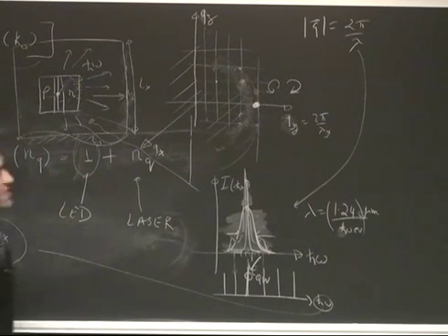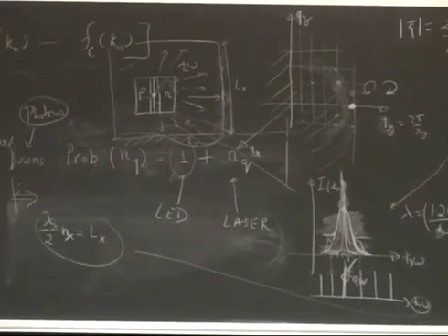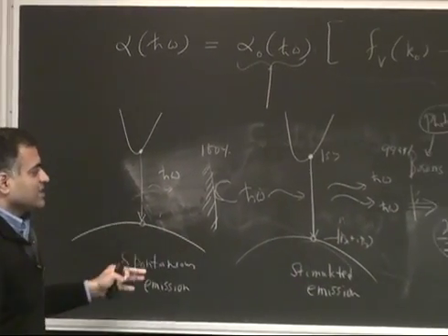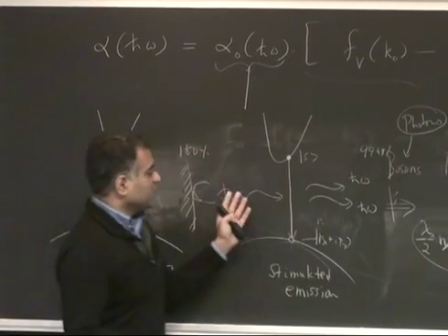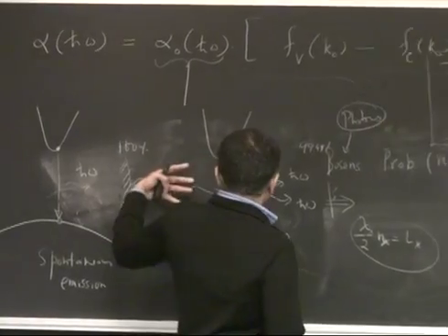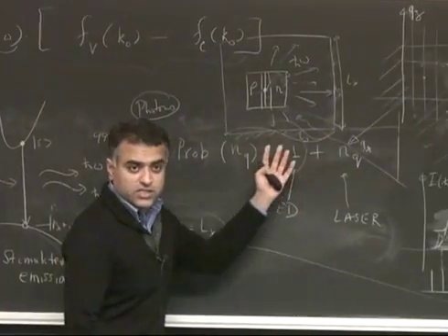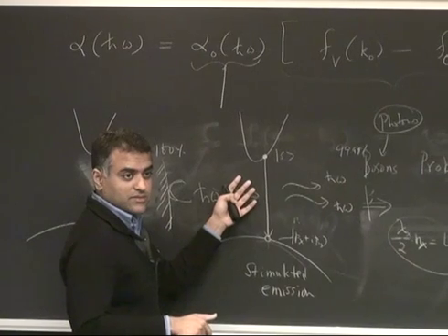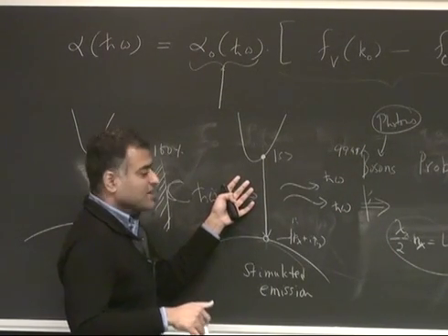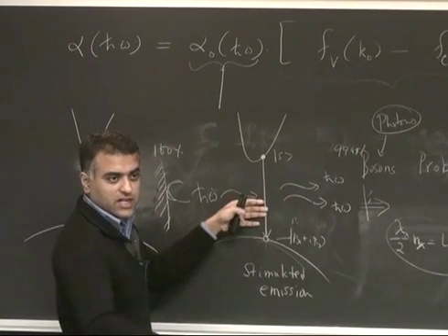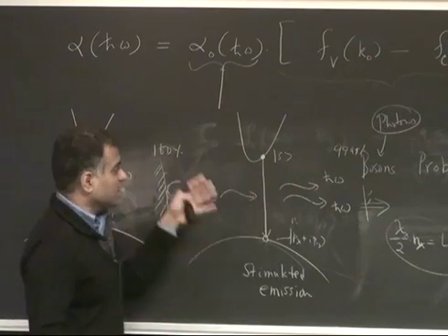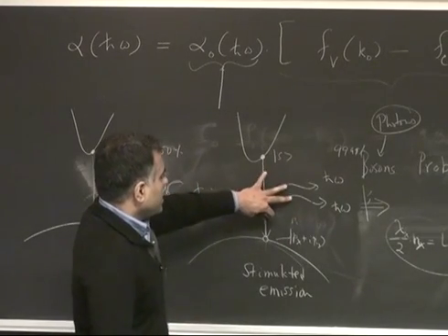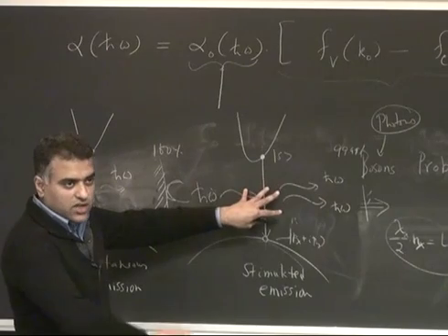Okay, some details there. What is most critical is, as the light passes through this semiconductor material where the light is being generated, it's also the gain medium, meaning the process of stimulated emission where 10 photons come in and 11 go out because of the bosonic nature of photons. First things first, this material must not absorb the light. For this to happen, the absorption coefficient must be negative, and only then do you have gain. So this media is called the gain media, and you want the light to pass through it multiple times. The competition is always between gain and loss.